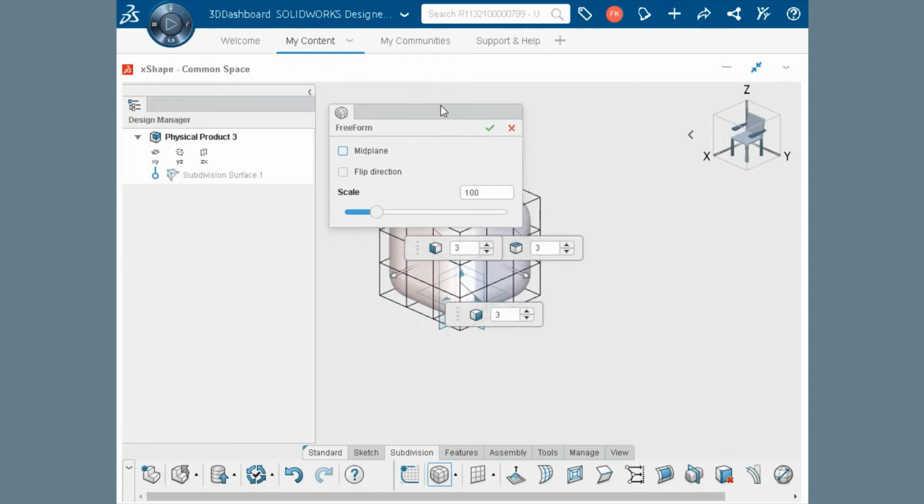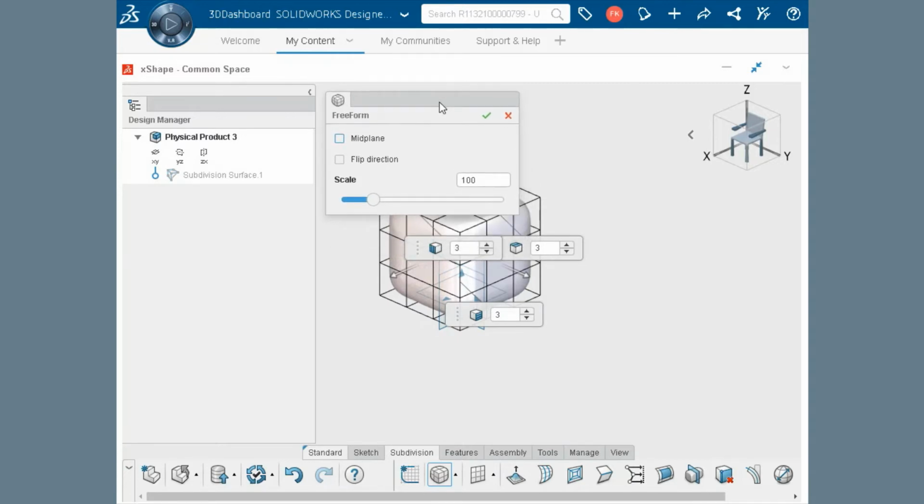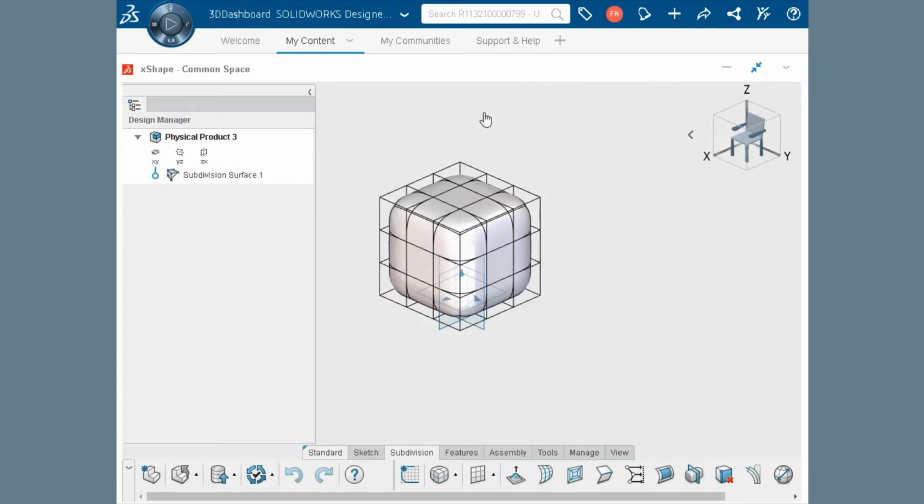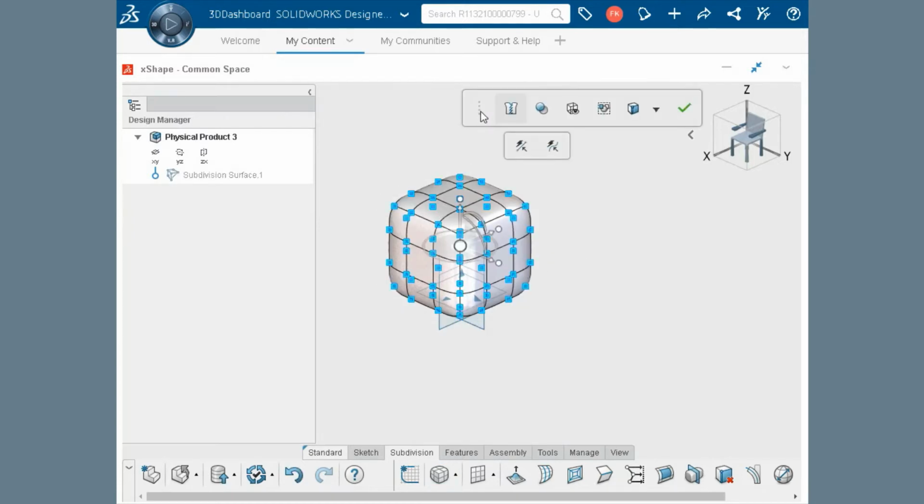The subdivision dialog, with the default placement settings and on-screen flags, appears. These settings can be used to modify the overall size and topology of the box. We'll use the defaults, so click OK. After creation, the entire surface remains selected, so I'll just click off to the side of the geometry to clear the selection. Another option is to press the Escape key.